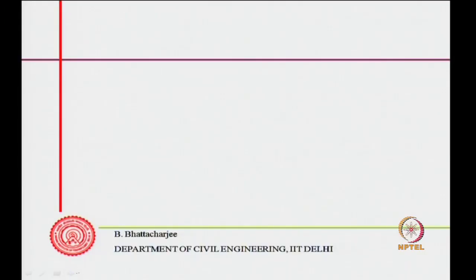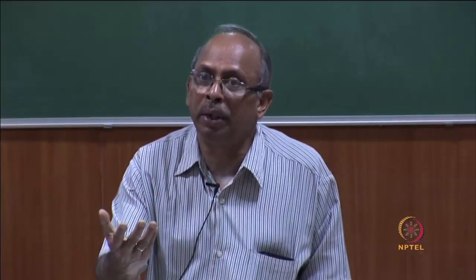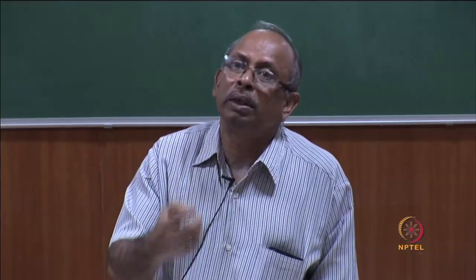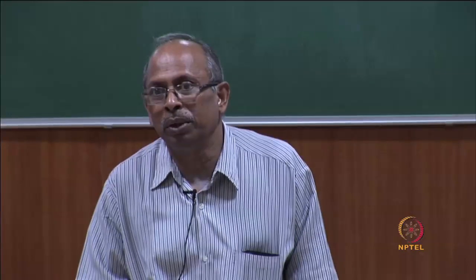So, similar kind of test one can do, and one can determine the particular superplasticizer. Then add this superplasticizer to get the slump you need. If you need still higher slump, then you have to increase the paste content, which means that you will increase water, cement, and correspondingly the superplasticizer dosage also.